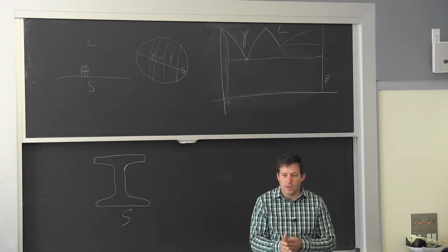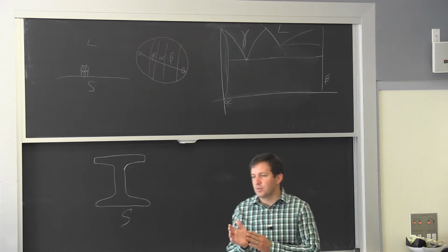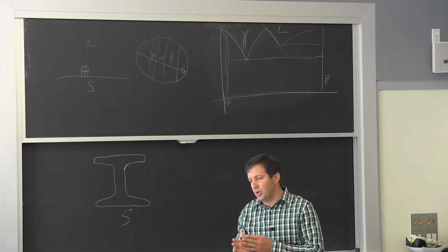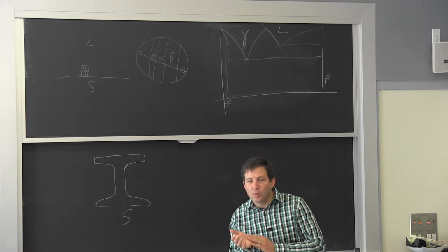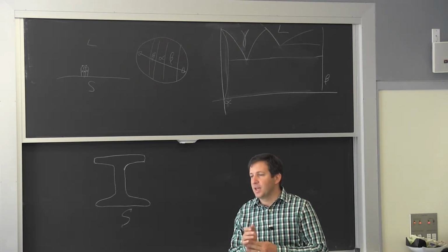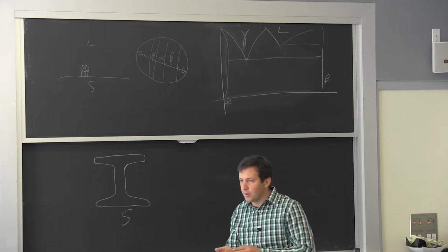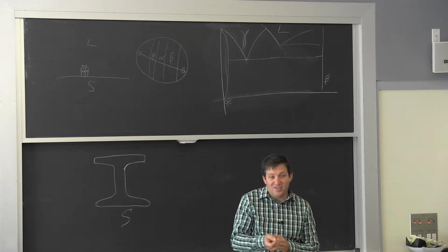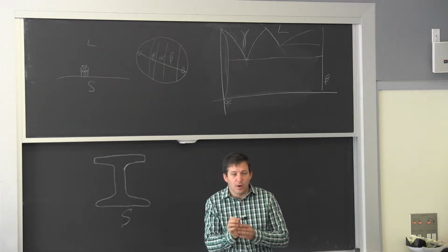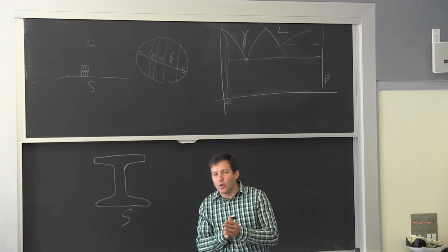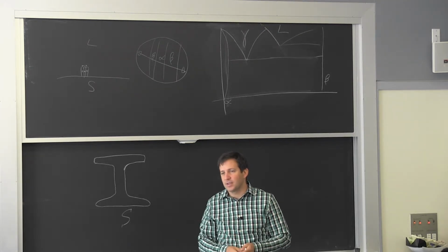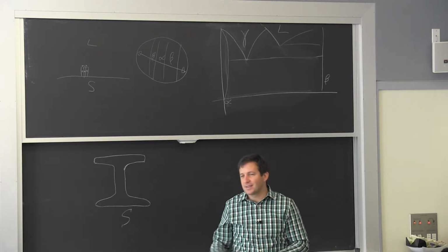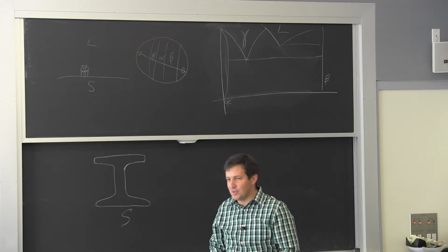But if you think of it generally in terms of the resistance to shear, the resistance to shear is very important in machining operations. And that's why we sometimes use resulfurized steel or brass that contains lead, because the small lead particles enable the formation of these voids, and it's easier to create that shear plane. So if you take leaded brass and you shear it, it's going to be a lot easier, the same way that it's easier to machine.